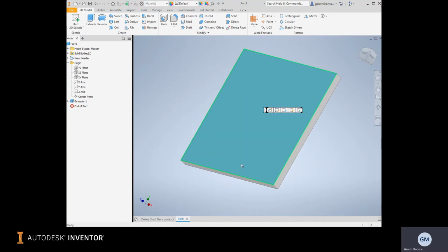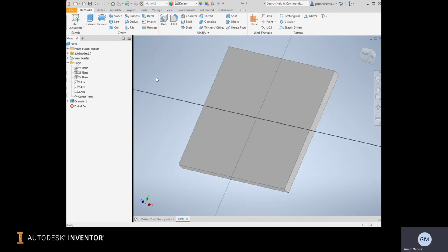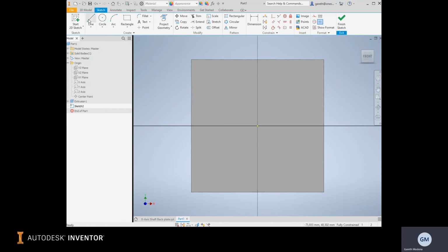So we want to draw on that. And we can use the Create Sketch button from the hotbar, this little bar here is called the hotbar. We can also click where we want to work and just press S on our keyboard. That's the keyboard shortcut for sketch. We want to map out our new edge that we want to work with. So we're going to just aim at the edge there, start our line, give it a rough size of about 8mm, left click for the end point, click and drag around our slot, come back down across there, and then we can form that up using dimensions.